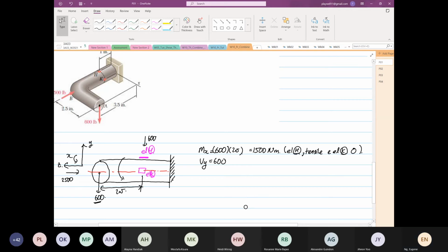They don't come. So for Vy, it's a circular pipe and it's straightforward, because now for a circular pipe, shear stress is equal to VQ over IT, right? You cannot use thin wall anymore. A pipe is a pipe, okay? There's no thin wall pipe. I mean, there is, but for this case, it's not, okay? So from here, what is his name?